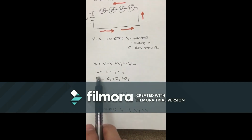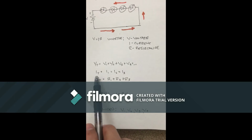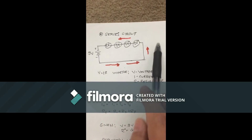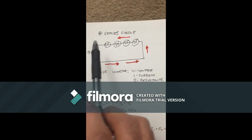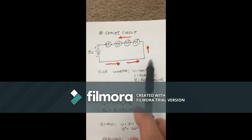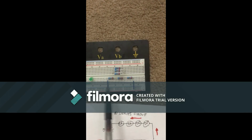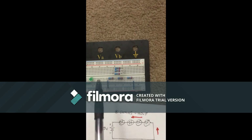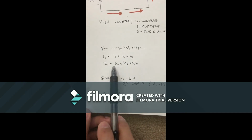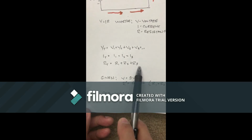To get the current for a series circuit, the current is equal throughout the circuit, since they're already in series. So the current running through this circuit would be the same throughout each load or resistance. And for the total resistance, we have to get the summation of R1, R2, and R3.